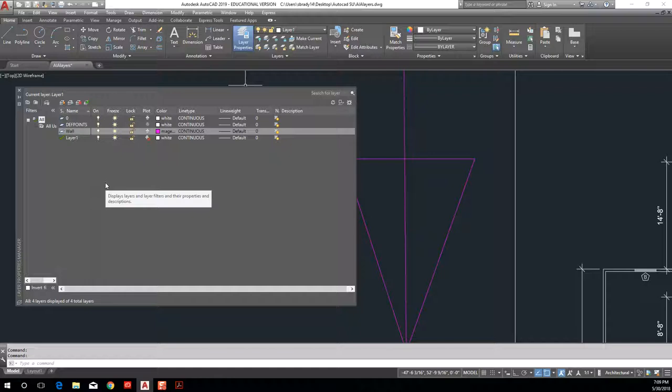Now, because it has such a broad audience and so many people are using it to do different tasks, I'm specifically talking about lines and line weights, colors, and objects in AutoCAD. Even the printing of the line weights is very generic, okay? What I mean by that is when I assign a color to a layer and then my lines turn that color, that doesn't mean anything to AutoCAD, all right? It means that line is magenta.